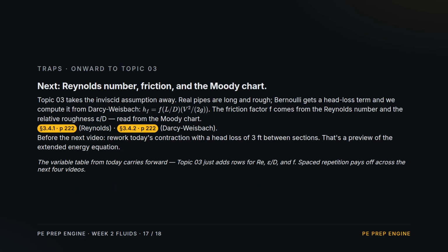Next, Topic 3, Reynolds number, Darcy-Weisbach friction, and the Moody chart. We drop the inviscid assumption and compute head loss from the friction factor, the length over diameter ratio, and the velocity head. Before the next video, rework today's contraction with a 3-foot head loss between sections, a preview of the extended energy equation.